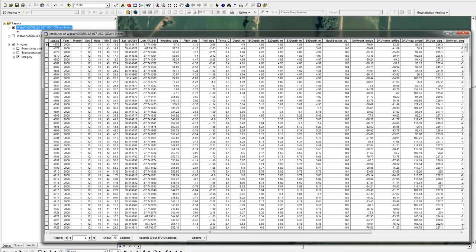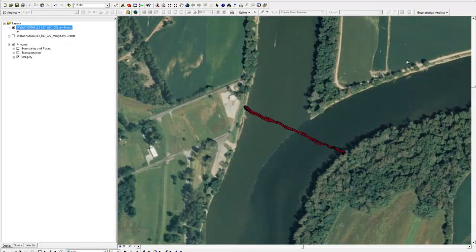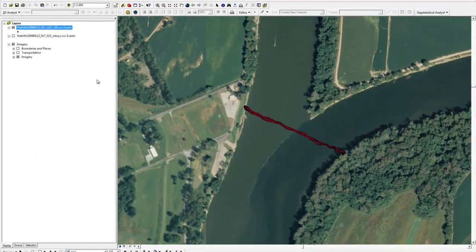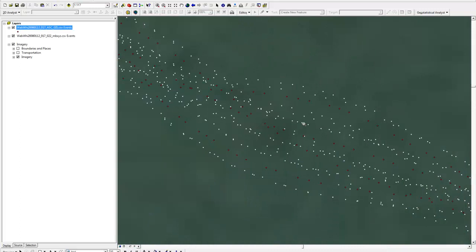Within the VMT utility, in the main VMT program, you have the ability to export multi-beam data, so you get individual georeferenced beam depths. And I've already done that in this case, and so I can turn those on here. They come into the GIS environment in a very similar manner, and it allows me to get individual beam depths for each of the ADCP beams. They're corrected for heading, pitch, and roll, and georeferenced based on the ADCP position. It's basically just geometry.